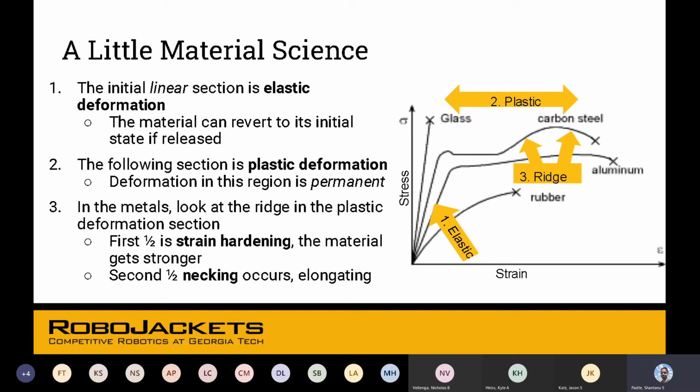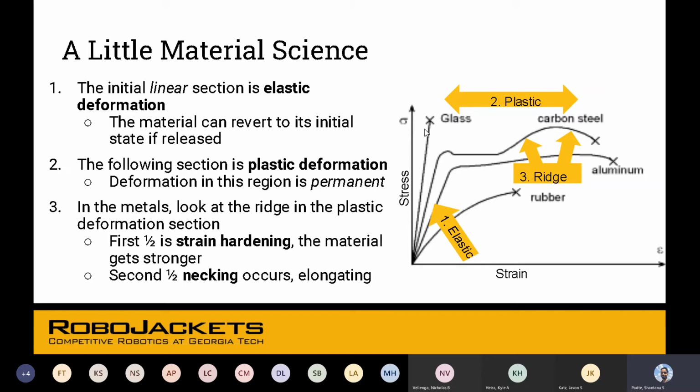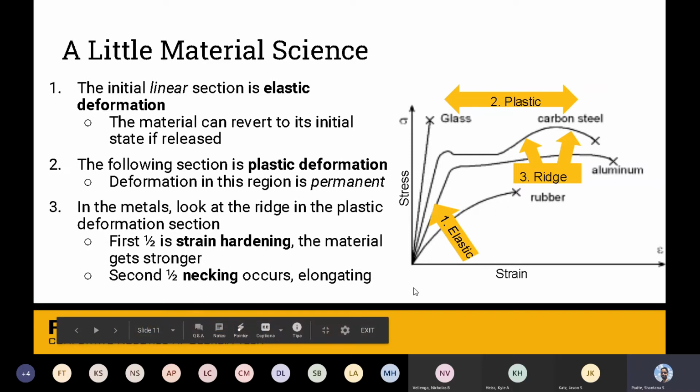You get it? So there is a word for these. It's called isotropic. So steel, aluminum. These are isotropic materials, which means their material properties are the same in any direction. And the opposite of that is anisotropic. Wood would be anisotropic. Glass and rubber are kind of wonky in this. I'm going to say they're anisotropic because it depends on the process in which they were made as well. There are a few different kinds of glass, and rubber also consists of stretchy molecules. And so I would say rubber is anisotropic as well.